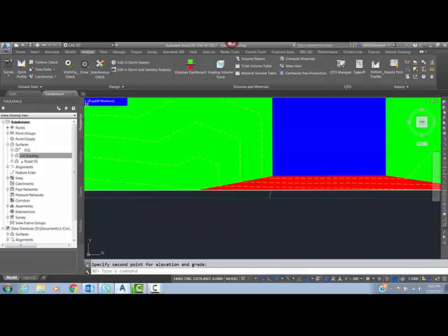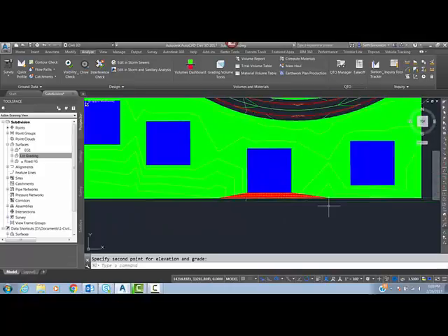So I could take a look at what these two points here are doing, adjust to see if I can fix it. Most likely the issue is because this lot pad is so far back here. It's not really in the best location. It's too close to the back. Now, since that's right at the tail, at the edge, I'd probably be okay with that.